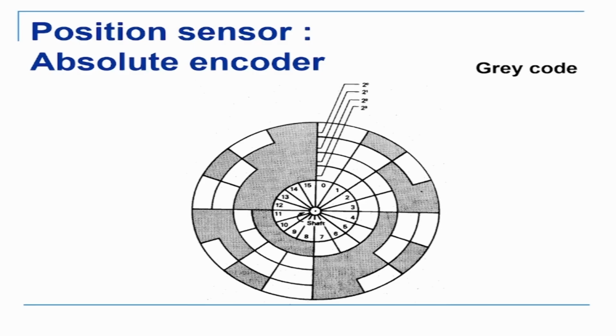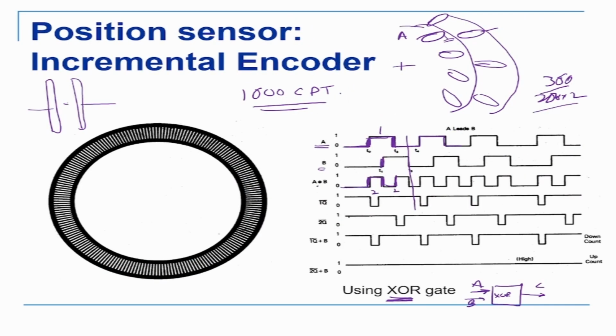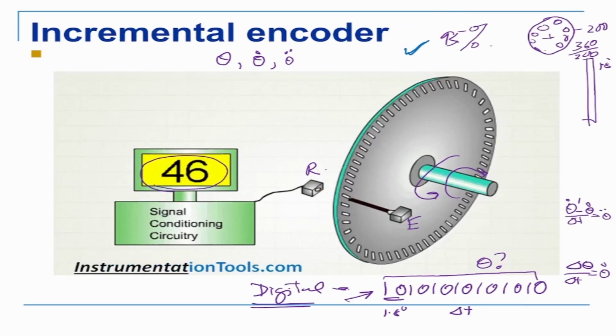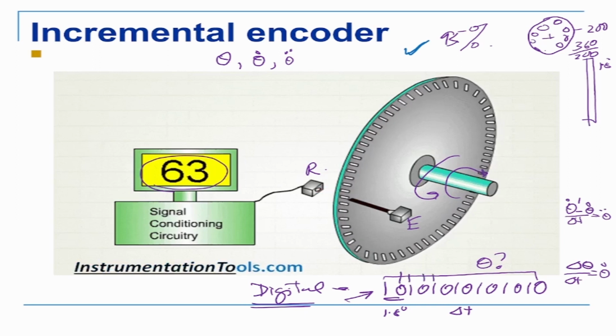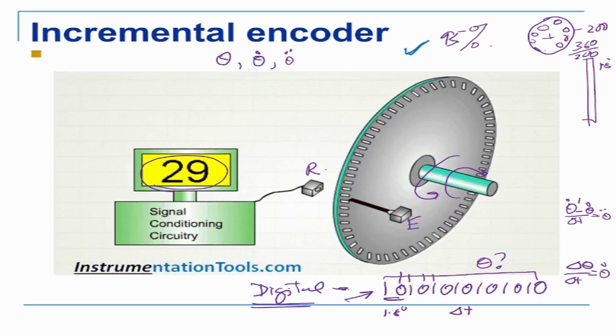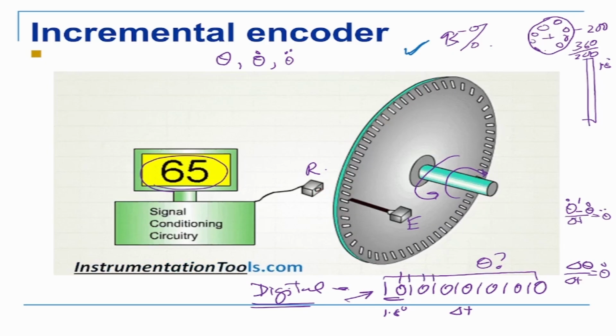Now, something to note here is that this is an optical encoder, an incremental encoder, which basically means that it is incremental in nature. So the signal is incremental. What that means is that it is 1 0 1 0 like this incrementally. With this there is no absolute position. For example, when the encoder is rotating and the power goes off, you won't know where the angle was, because it is an incremental device.